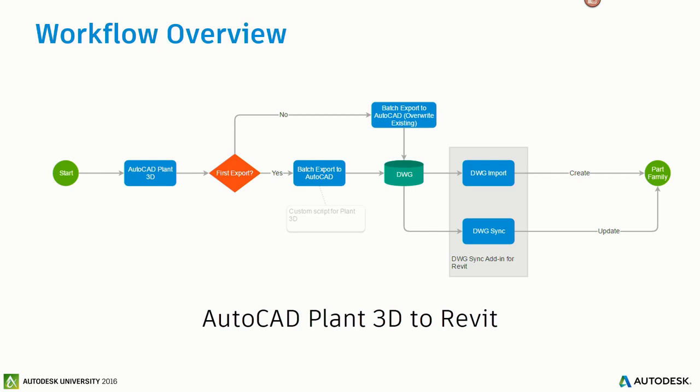On that, the workflow that we use is we start with the Revit, push the Revit out, and then the plant guys model from that. So whatever coordinate system you're using within Revit, the plant guys just model to it. Be very careful about Plant 3D and ISOs in your coordinate system. That's true, because if you shift that, it throws everything off. Something that small, as a coordinate system, will screw up your ISOs.